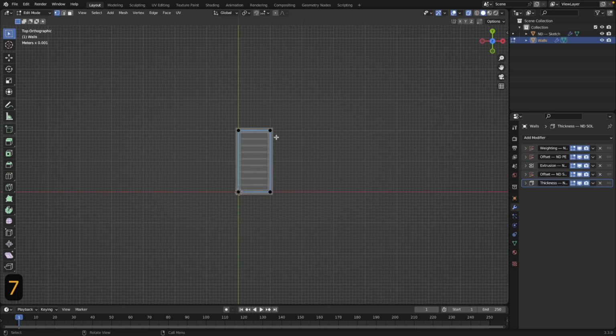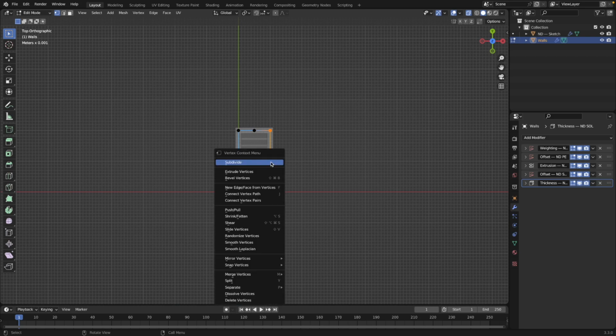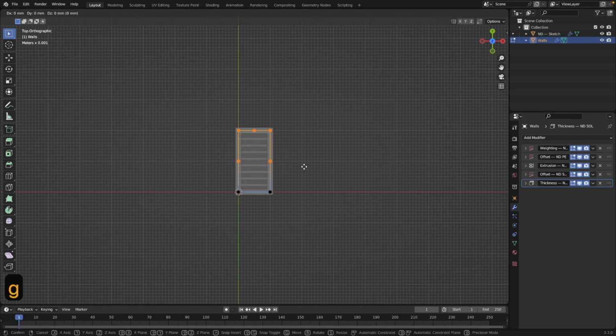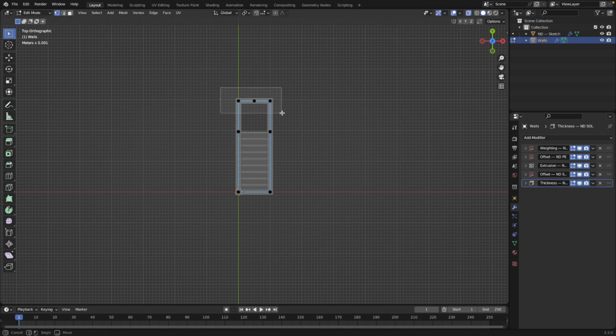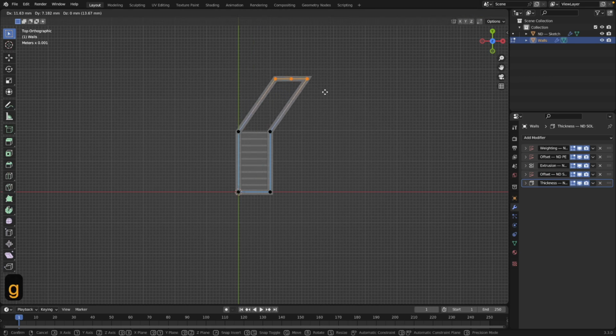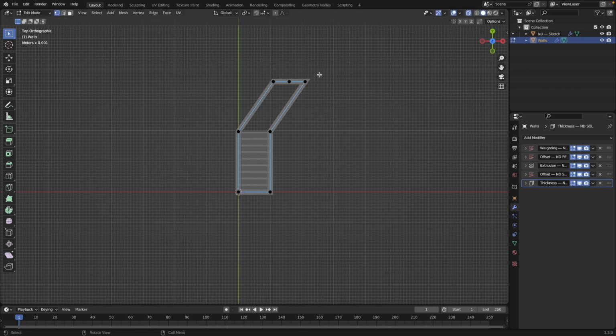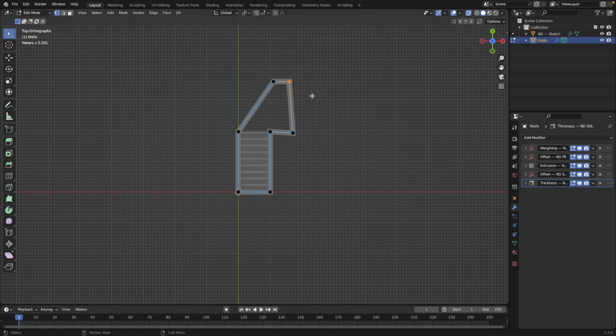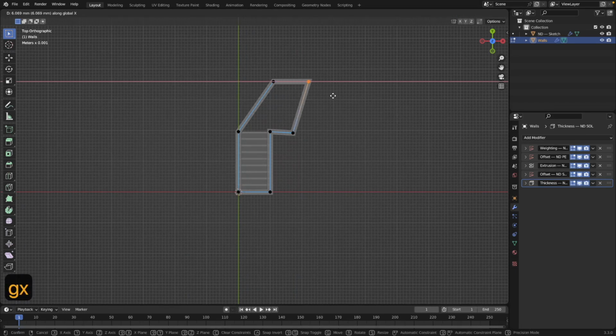What I'm gonna do is I'm just gonna tab into this rectangle shape. We're gonna look at it from the top view, and I'm gonna add some extra points by selecting some of these sides and subdividing them. That way it'll give us a few extra vertices to play with to make a more interesting shape here. So let's make the whole thing a little bit bigger by moving these up along the Y-axis like so, right? That seems good. And then we'll move these over this way to create an angled shape. Let's move this one down out of the way for a second. Yeah, move this along the X out this way.